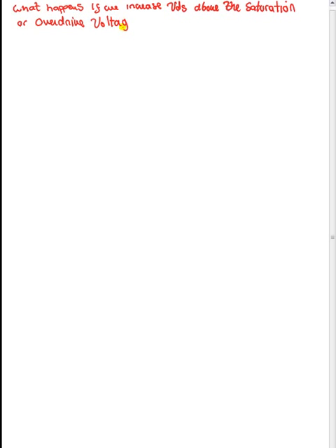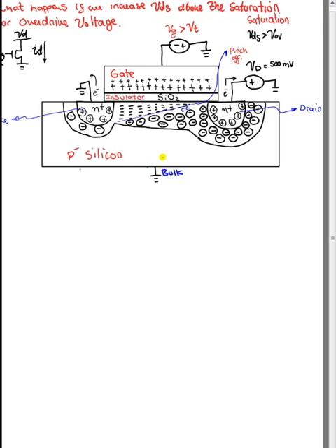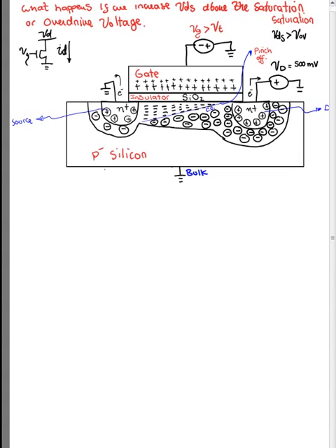And so here's again our little transistor in the high level view, and now we're gonna draw our visual diagram. We still got the ID going on. Okay, so here is the diagram, and let's note that the transistor is operating in saturation region because the drain to source voltage now is greater than the overdrive or the saturation voltage, right? The gate voltage is still greater than the threshold voltage, which means the transistor is on, right? So now let's take a look at what's actually happening. So when we run the experiment again, what do we get?